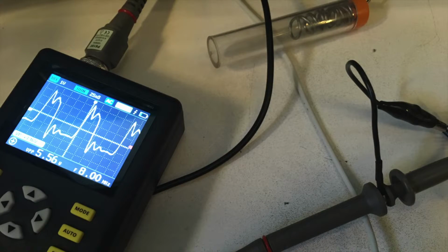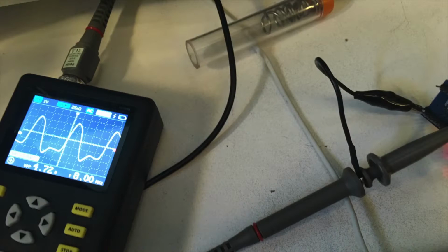So here's an 8 megahertz square wave with the included probe in 10 times mode. It's pretty much what you would expect. Same deal when we switch to 1 times probe, because obviously we're losing our bandwidth there, so we're rounding off our square wave a little bit, and it seems to make it look as though it's a pulse or has a different duty cycle. It actually doesn't though, which is a little strange.